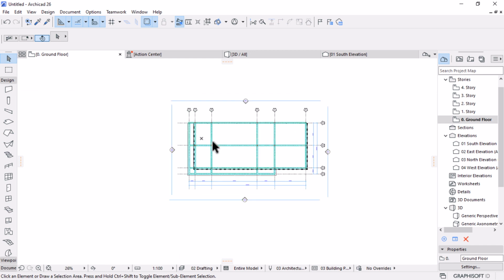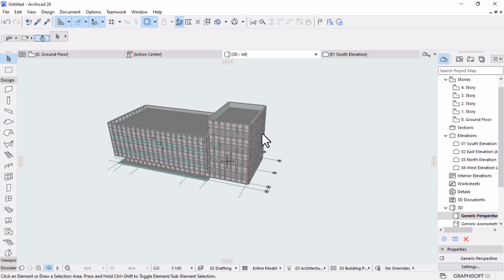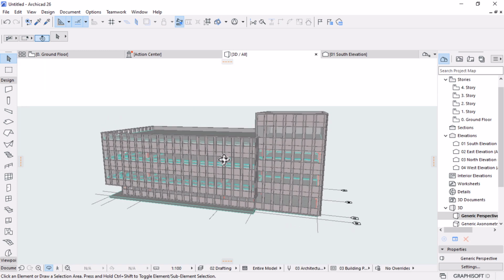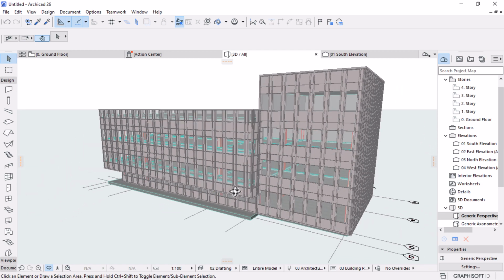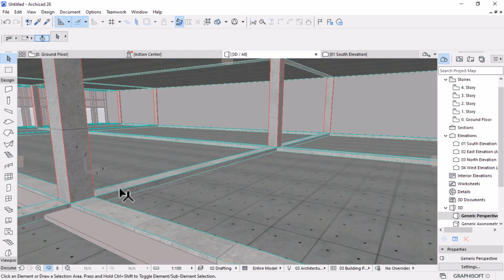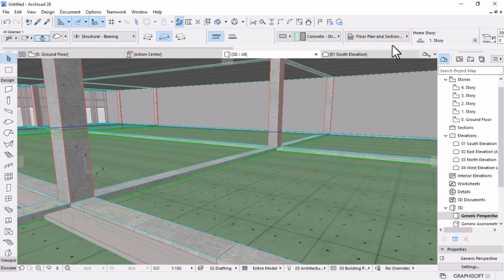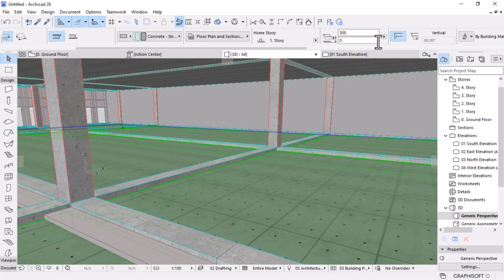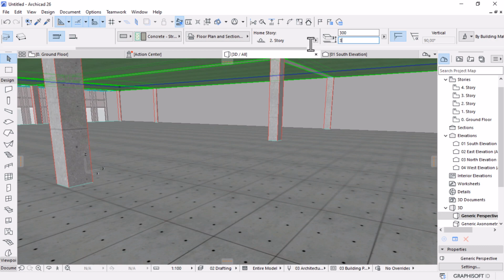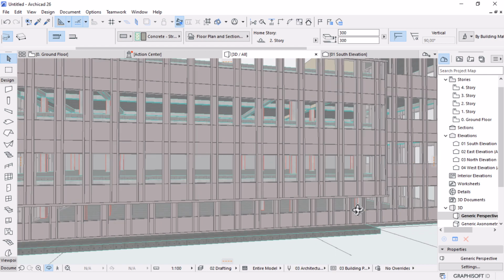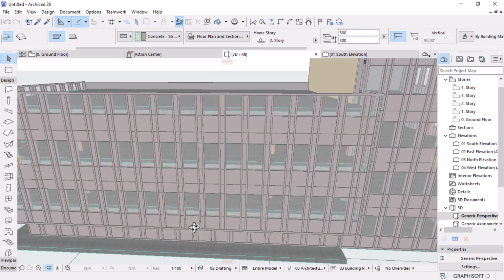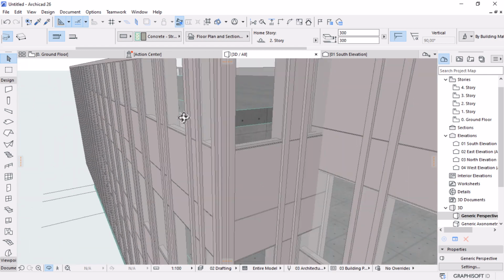and then what we need to do now, if you look at the 3D, let's go back to 3D. You find we just used a default curtain wall system for everything, and I don't know why all my slabs are underside of the beam. They are supposed to be on top, right? So this is supposed to be, I would say, 300. Same applies to this one, should be 300 up, yeah, because these are floor slab, right? They're supposed to be sitting right on the top of the beam.